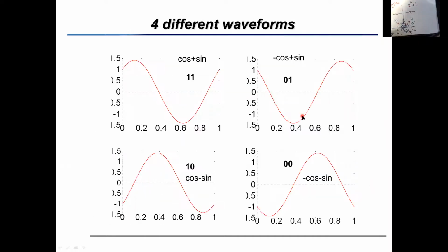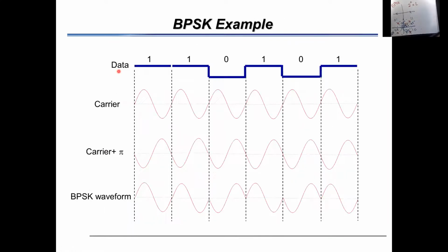So whenever you transmit this signal, which is a sinusoidal signal with a 45-degree shift, that means it represents a state of 1-1. Now I think you can capture the difference between the QPSK and the BPSK. In the BPSK, we have 2 states, and in one symbol duration, so now it's better to call it Ts, not Tb. Ts is the duration for one symbol. So here, the duration for one symbol includes 1 bit.